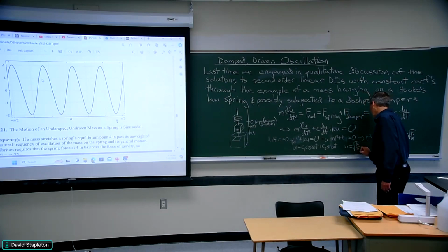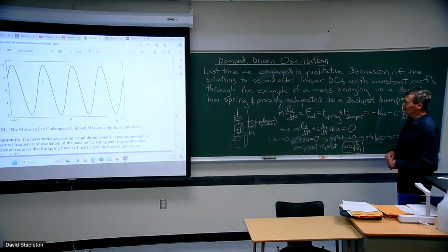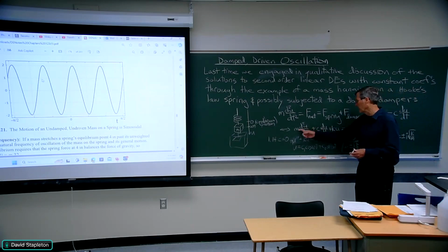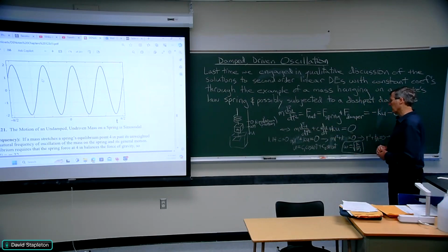This is a very interesting thing about mathematical modeling. A mass spring system without any damping will move exactly the same as long as K over M is the same. So if you double the mass and double the spring constant, it moves the same as the original system with the original M and K. If you quadruple the mass and the K, so there's really only one free parameter here. It's omega, square root K over M. That determines the motion of the mass. So we say it's a one parameter system instead of three parameters, right? One of them goes away by dividing through, and then the other one, instead of two parameters, one of them goes away by dividing through.